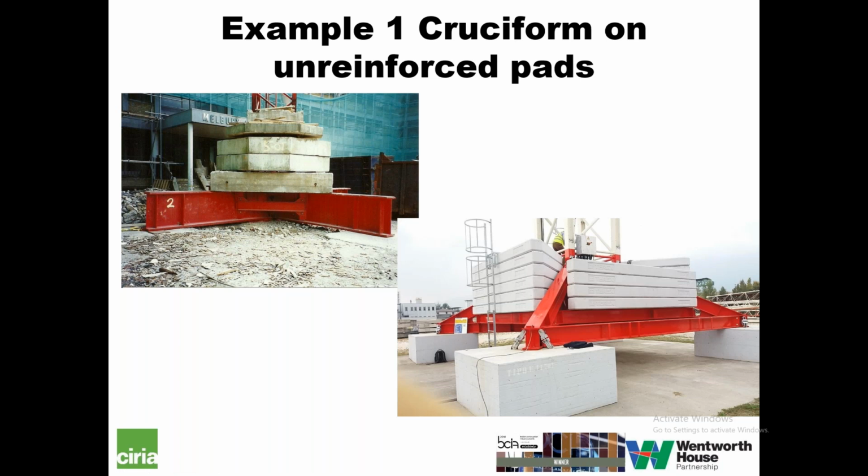However, it was found that these did slowly walk off their supporting pads, because in fact, under certain conditions, there is no load between the beam and the pad. And with the torque added onto it, it could move along slowly. So the recommendation now is that these are always restrained against lateral movement.